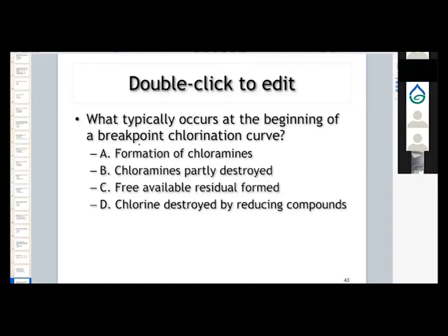But as you keep on feeding chlorine, the residual will go up. And what's actually kind of interesting is it will reach a point where it will actually go down. And that's when it's forming a different type of chlorine compounds, the dichloramines and trichloramines. And then once you satisfy all the nitrogen in the water, you would have met the demand, and then you're going to start forming free and available chlorine residual. I didn't include a breakpoint curve on here because the state questions won't ask you that. But once you get to a utility, and especially if they chloraminate, you'll get to know that very well.